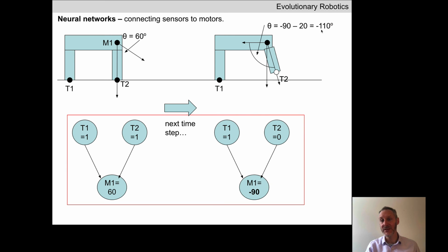It's a big difference. The magnitude is high, which means a lot of torque is going to be applied. And the sign of the difference, positive or negative, determines whether the torque is going to be applied to try and rotate clockwise. A positive difference is going to cause the motor to rotate clockwise, and a negative difference is going to cause the torque to be applied to rotate the object counterclockwise.